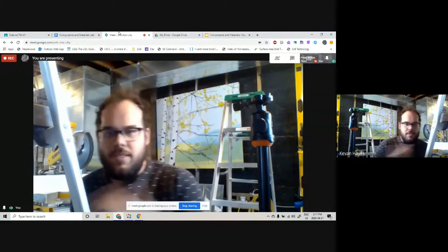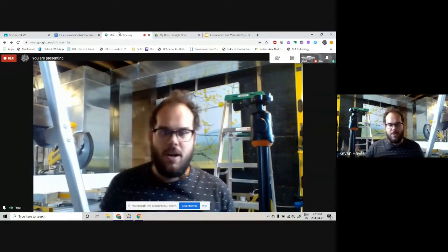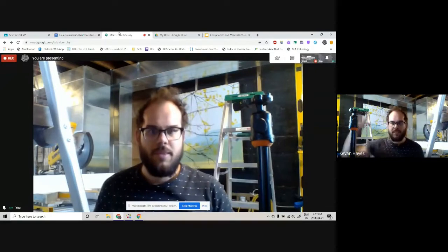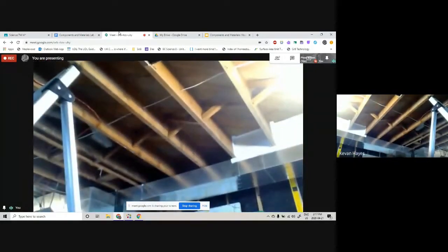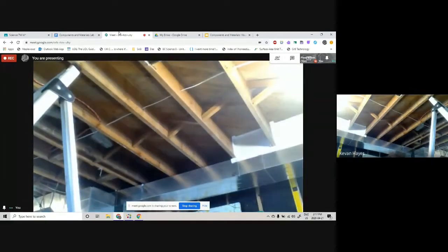And what you'll notice if you have a basement in your house where you can go down that doesn't have drywall in the ceiling, like this one here, you'll notice that this is how we build the structure inside of houses as well. So the floor is supported by a bunch of pieces of wood that are on edge. In this case, we actually call these joists, but they're essentially working like a beam, so they're carrying a load across a distance.